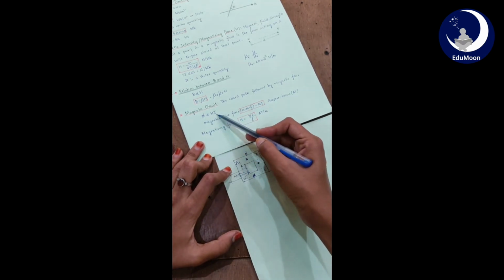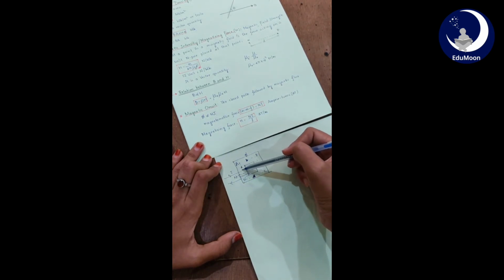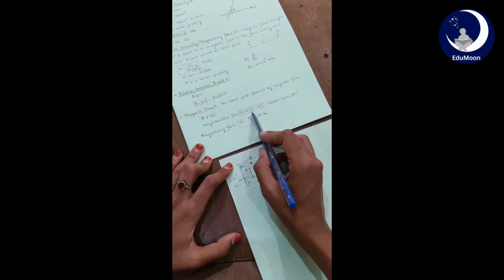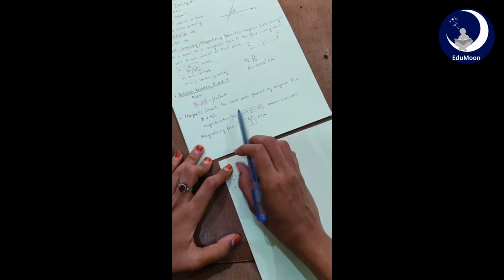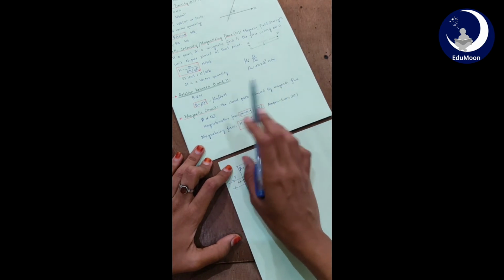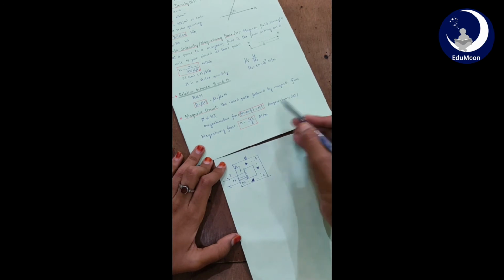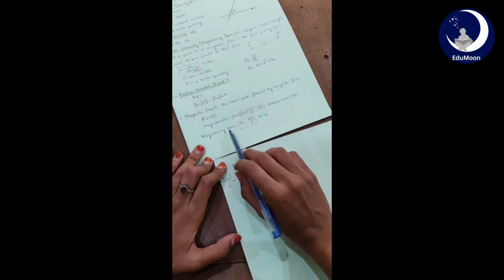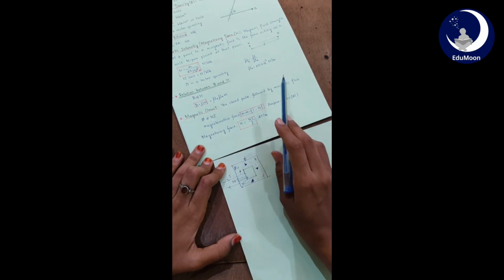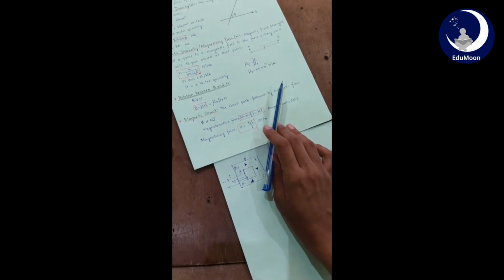So phi is directly proportional to Ni, that is, the product of the number of turns and the electric current I passing here. This product Ni is also called MMF, which is magnetomotive force. We will learn the proper definition within a few minutes. MMF has units of ampere turns, in short AT. Magnetizing force H is Ni by L, so its units are ampere turns per meter. We will learn about this in detail in the next few minutes.